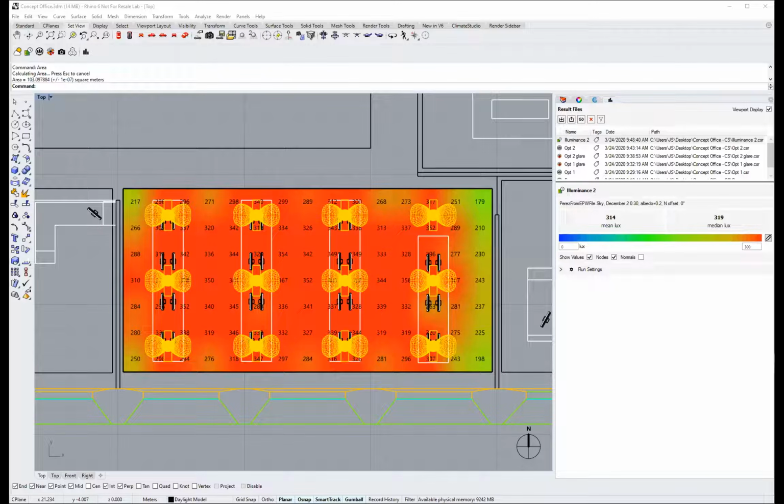The difference, again, as John pointed out, is that we're using path tracing, which is a method of getting the results very quickly. What that means is that as you follow the results on screen, you see them changing quickly. And as you see the results changing less and less, you know that they have converged. And once the tool notices that the results don't change anymore, the tool stops by itself. So in a nutshell, we're using Radiance with the three-phase method.